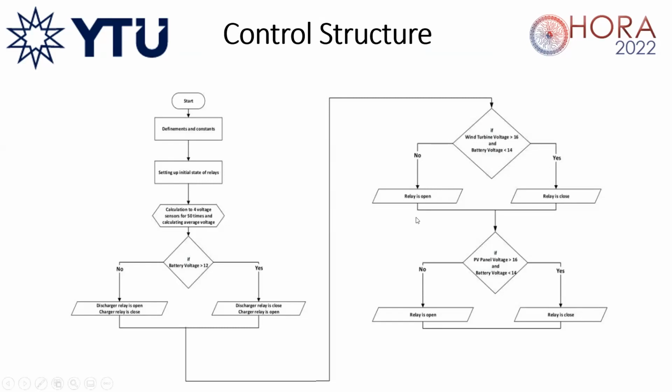One of the main purposes of the hybrid energy system algorithm is to ensure the continuity of the system stability and to protect the battery condition. For this purpose, the charge level of the battery is checked frequently to avoid overcharging and undervoltage situations. Renewable energy sources are disconnected from the busbar when the battery voltage rises from average to higher voltage, so that the battery is not damaged.